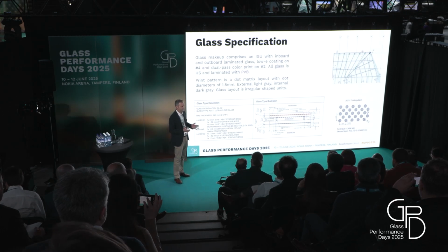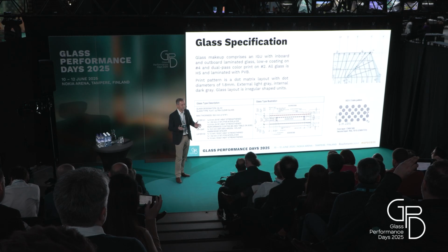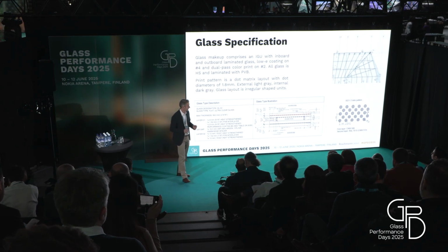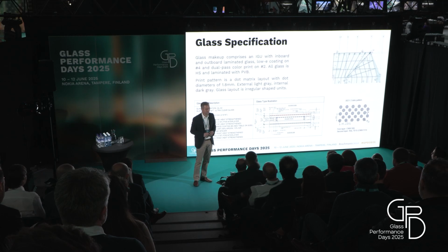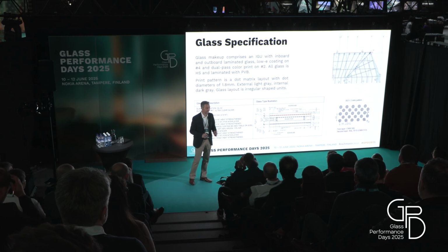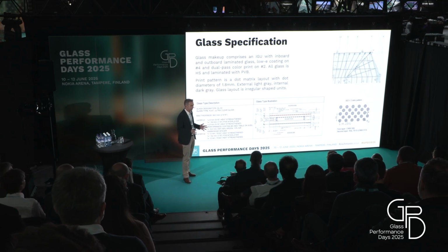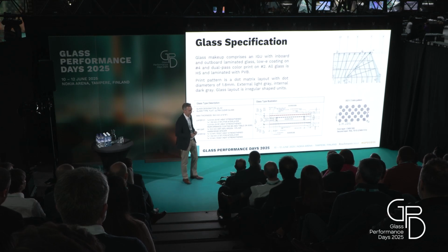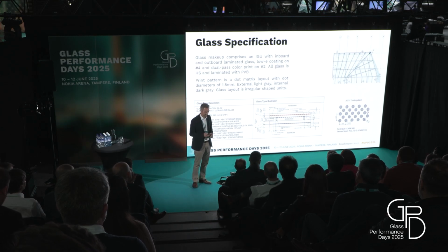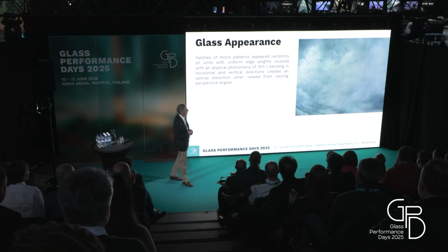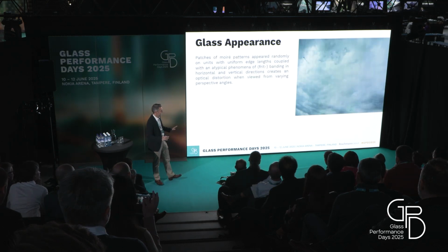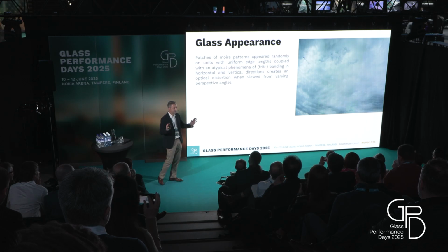And when you approach a glass fabricator with something like that, he will say, oh, you know what? This 1.8 millimeter dot, go to hell, we'll start at 3 millimeter, right? So in this particular case, we turned it over and said, well, can you do that? Well, we shouldn't have done that. So of course, the glass appearance looks like that. Not all the time, but in some conditions.